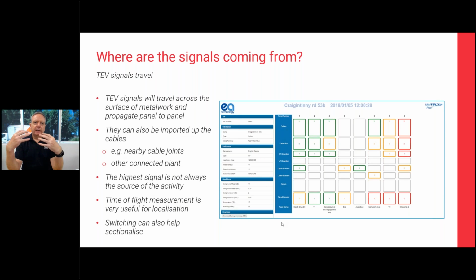So as you can see there, we found discharge activity on the outside of cables around a transformer, and we've got two very different sorts of defects. One's on a joint, one's inside the transformer. You can quite easily jump to conclusions, and this is where people sometimes fall down. Probably the biggest failure mode of parts on switchgear is cable joints. So is the terminations. So people often will jump to the conclusion of just replacing a termination and maybe carrying out some activity which is actually not relevant and is not going to solve the problem.